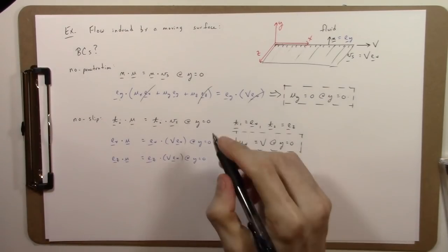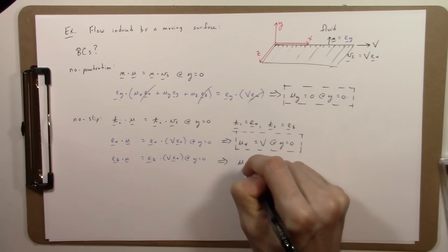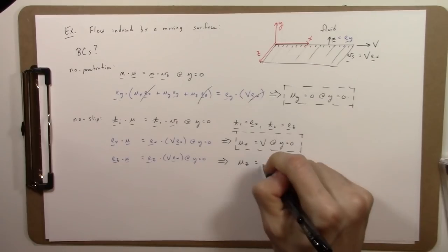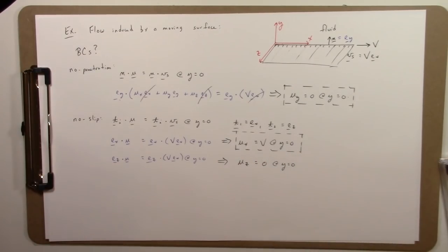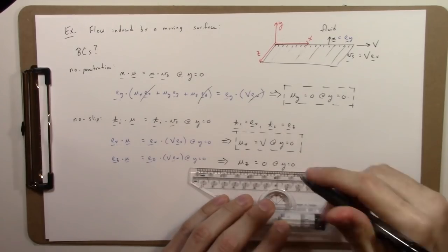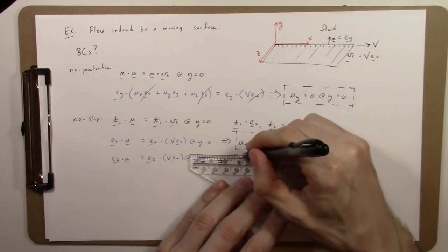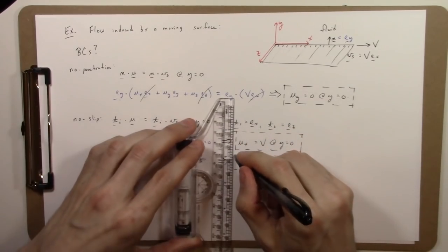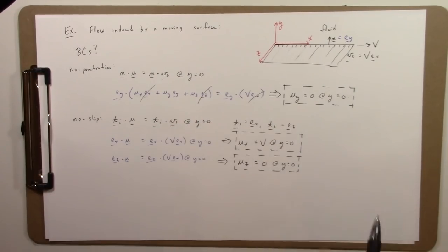The z component of u is uz, and ez dot ex is 0, so uz is equal to 0 at y equals 0. So that's the final component of the no-slip condition for this system. In general, for 3D flow, there are two no-slip conditions and one no-penetration condition.